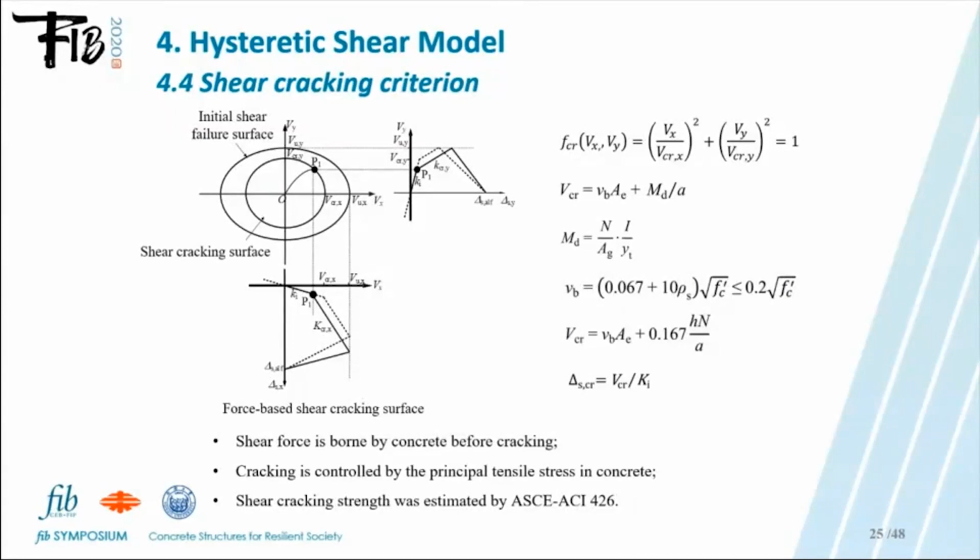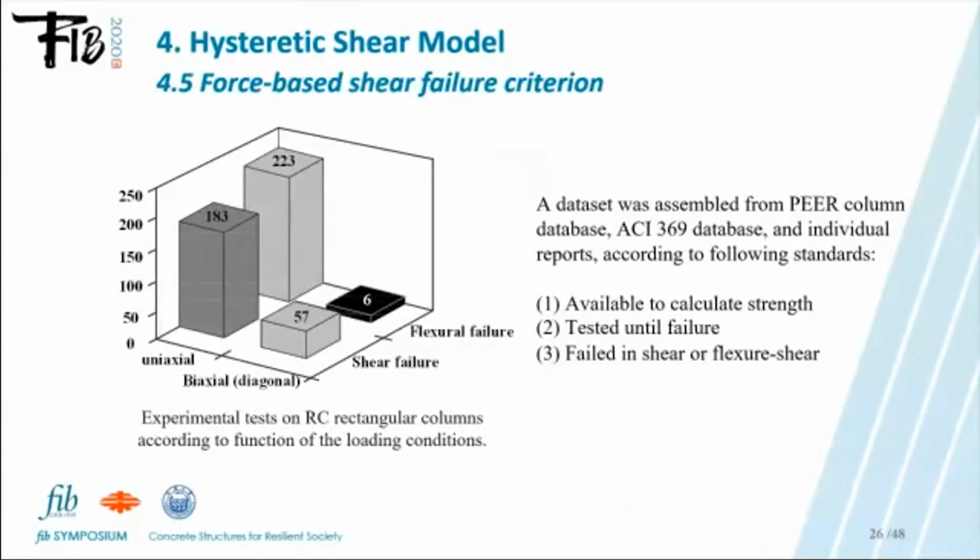Shear cracking strength was estimated using a formula for the shear cracking strength of columns in ASCE-ACI 426. The corresponding shear displacement at the cracking point was calculated using the formula from elasticity mechanics.